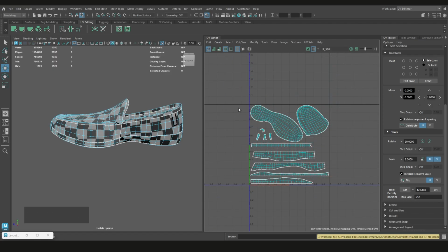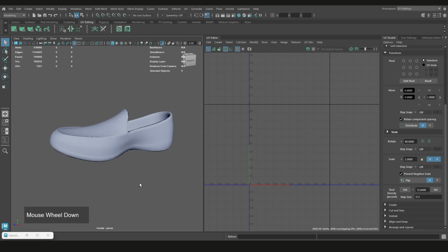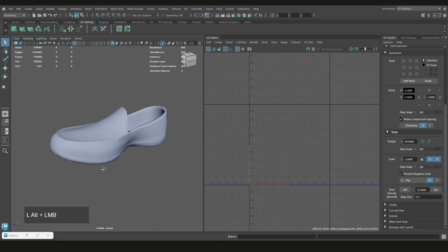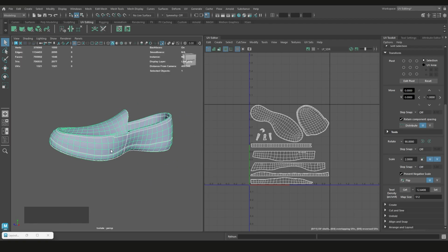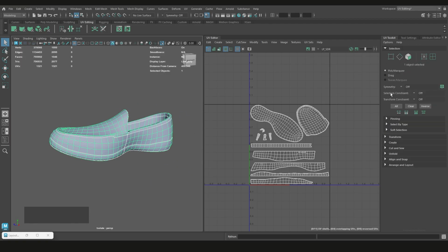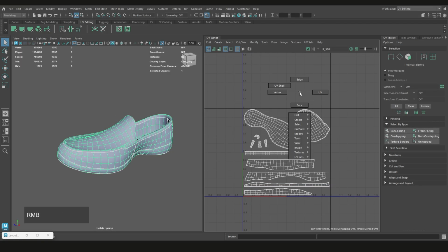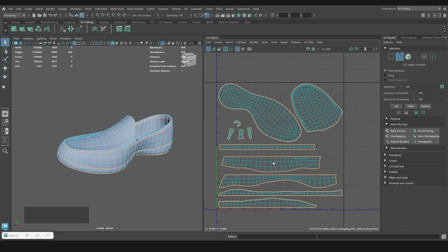So up next, let's switch this off and go to object mode and Alt-Shift-D, because we've been doing quite a bit there. So now you notice this whole thing is smoothed out, right? There's no hard edges or anything of that sort, okay? It's just all one piece. So what you want to do is go on over to edge, right? And then say select texture borders, right? So this is going to select the borders of all of this stuff here, all right?